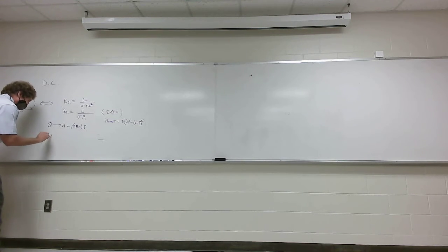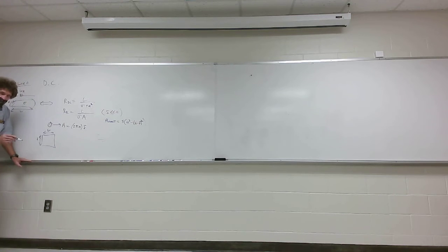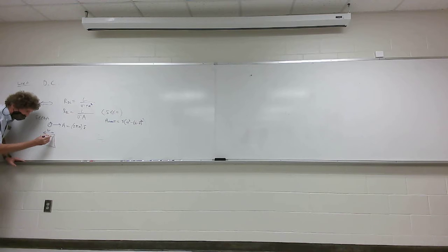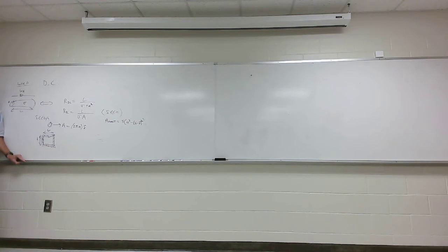If it is a rectangular cross-section like so, where we have a width W and a height H, then just think about this. If we have this condition right here, if the skin depth is much less than A, then in this case it wouldn't be A here, it would be W or H. In other words, it's something small compared to the geometric dimensions. Then you just go around the perimeter here. Can you all imagine this here? And that would be the area the current flows through. You all see that, class? Can you see it back here?